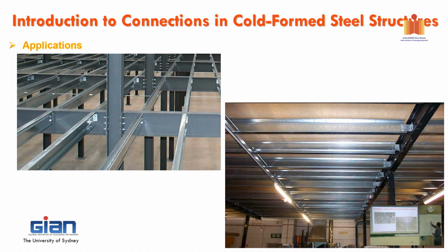So what you do here, you actually move that bolting close to the web. The idea is that the more you reduce the eccentricity, the better. Cold form steel is a little tricky because the section is going out and it's hard to chop on the top, as you can see here. That's why in here you can see the top one to the flange, you've got a bit of distance. And then you have to connect by the angle here, the angle clip.